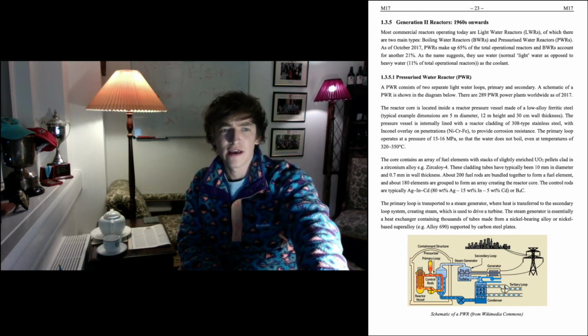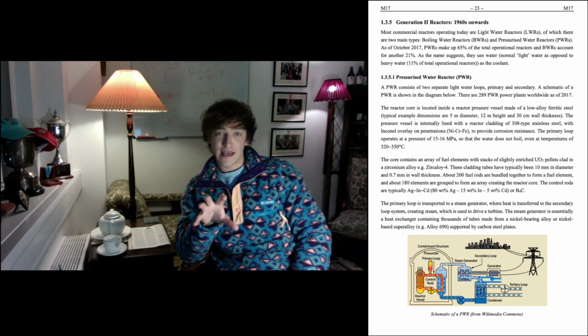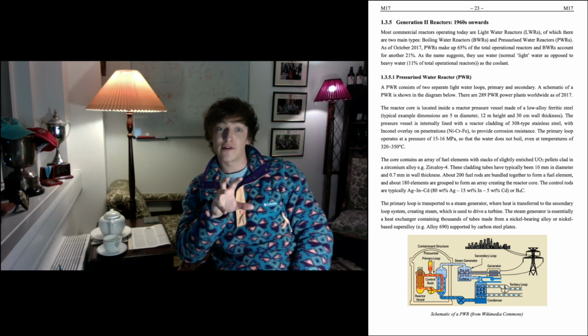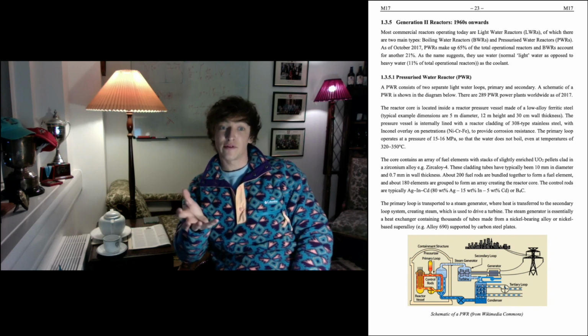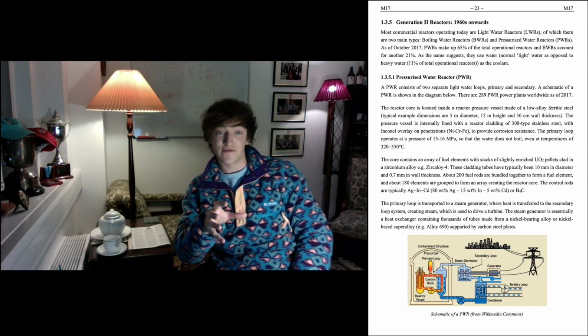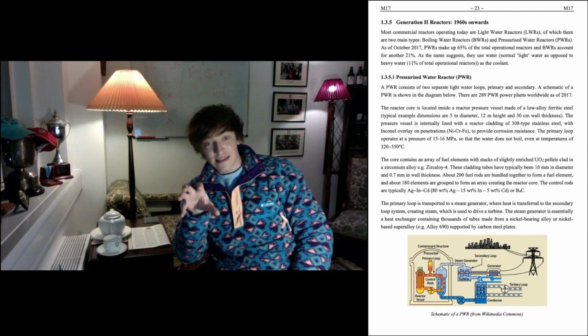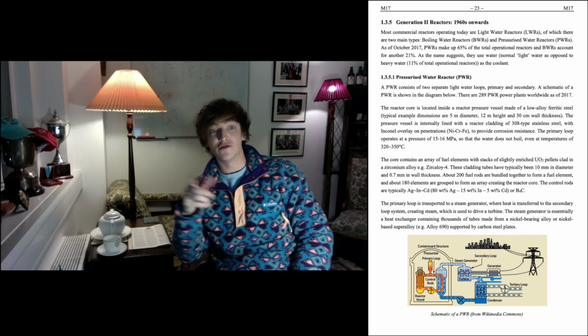How does a typical PWR differ from that of a Magnox reactor? Well, if you look at the schematic I've provided here on page 23, you'll see that a PWR has two separate loops. You've got the primary loop, which is pressurized to around 15 megapascals, and that's done to prevent the water from boiling, even at its operating temperatures of around 320 to 350 degrees Celsius. And then you've got the secondary loop, and that secondary loop runs at a lower pressure to allow the formation of steam to run that turbine.